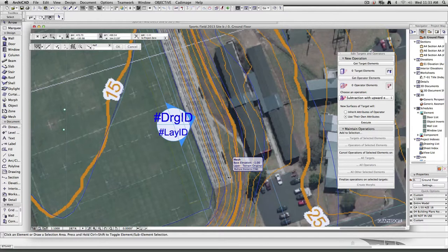So we need to know what the height difference is, which is relatively easy here because we can go 15, 16, 17, 18 metres. So the top is 18, bottom's 15. We can do some math. 5, 6, 7, 8, it's 3 metres. So we're going to go up 3 metres. If we had 10 steps, there'll be 30 centimetres each step. Cool. So that's what our rise would be. Then we've got the run, which we could also measure off this plan. However, let's just have a look at this in a much easier way.